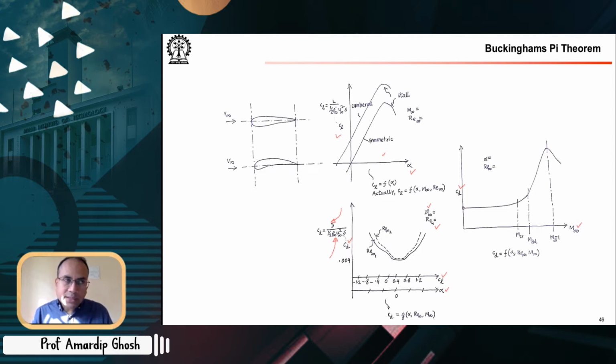And I must say at this point that eventually, we will also see another approach where we start with a governing equation, popularly an ODE or a PDE. For example, you can start with the Navier-Stokes, or you can start with the Euler equation, and you apply a similar kind of thing. We say normalization and non-dimensionalization. When you do that, some of these non-dimensional groups also come out of the PDEs or the ODEs. And there, these are not only non-dimensional groups, but groups that have important effects on the problem at hand.